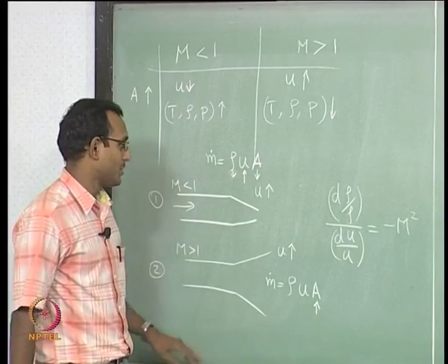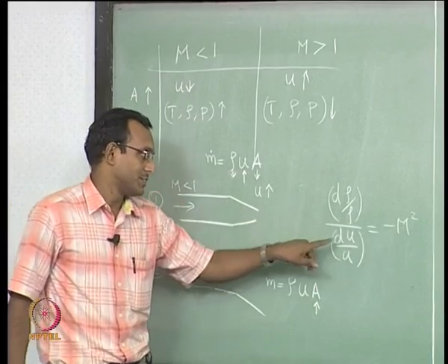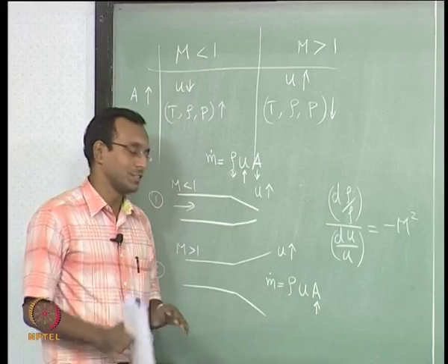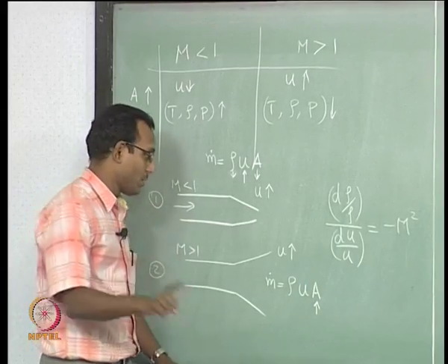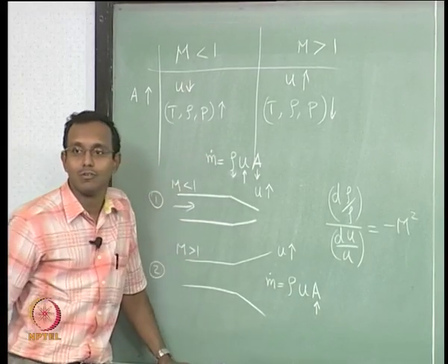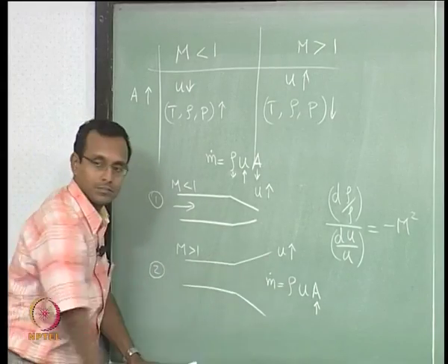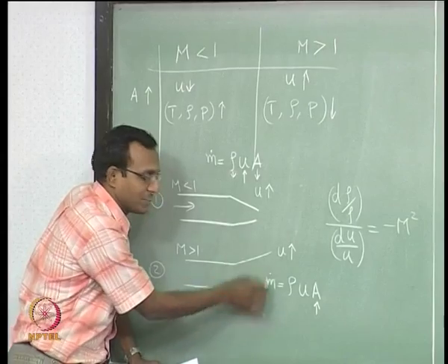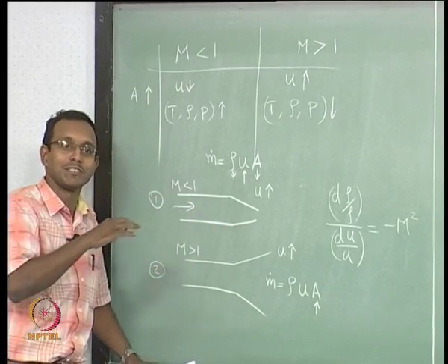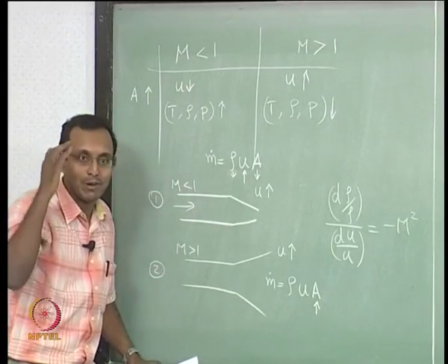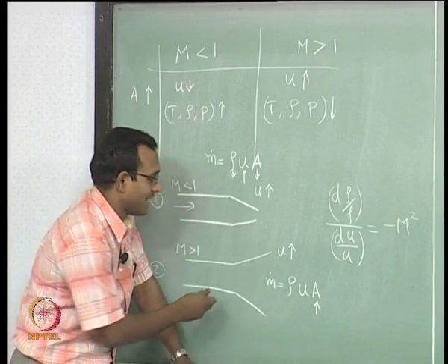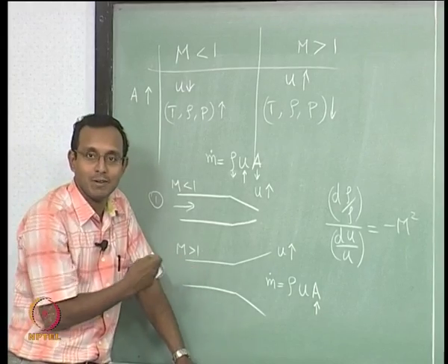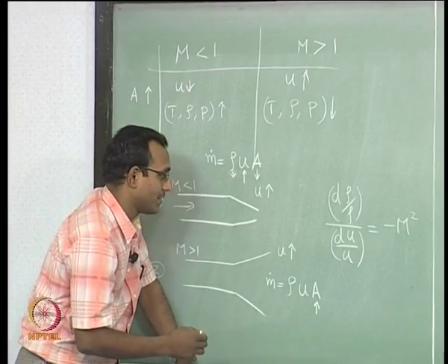Okay. I am going to say Mach number is high, which means for a small change in u there is a huge change in density, and they are going to go opposite direction. Overall, it has to make the same mass flow go through this whole duct. Of course, remember it is 1D flow, so it is going to occupy the full region with uniform velocity and all that, it is quasi 1D assumption, remember all that. Okay. In reality, the flow may separate from a wall and just get out, we will not have such things in our 1D world. Okay.